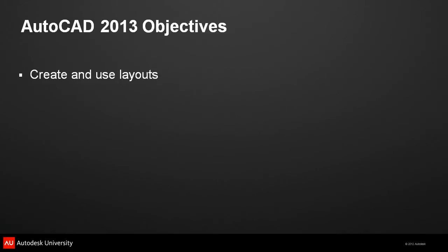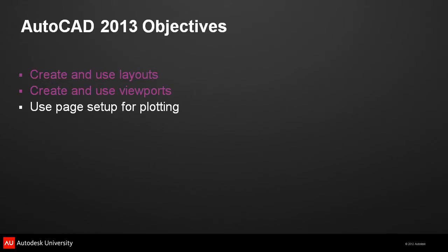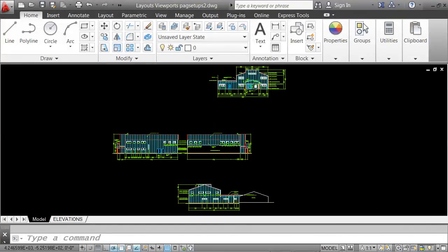Our final objectives are to create and use layouts, create and use viewports, and use page setup for plotting. So we're going to look at these three to close out our session today. Let's address the first objective, which is to create and use layouts.